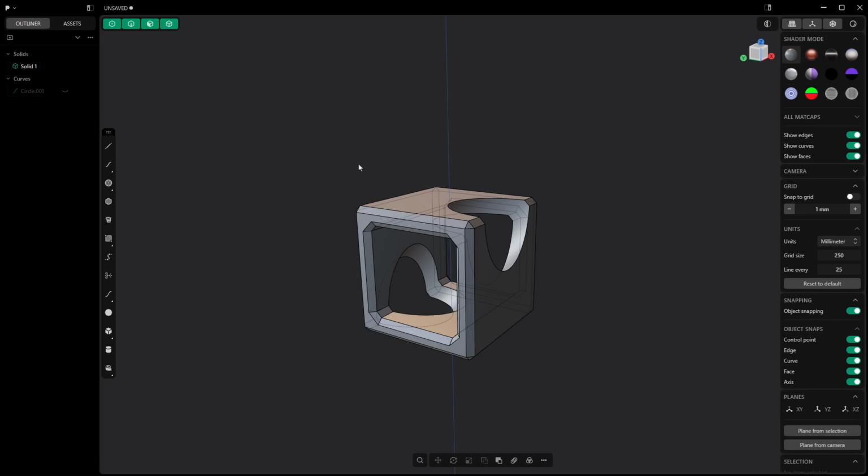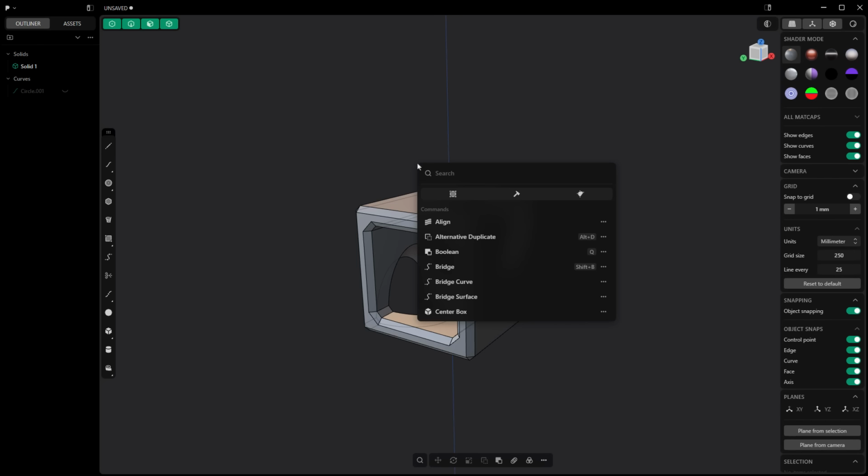First, the F key. The reason I think it's important to know that rather than to come down here to click it is because it'll show up wherever your cursor is. This is a quick way for us to search for commands. So for example, raise degree. It'll tell you what the shortcut key is, and if you want to add it to your favorites, you can click Add to Favorites.